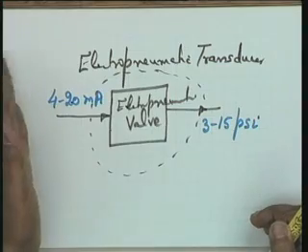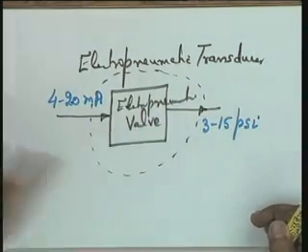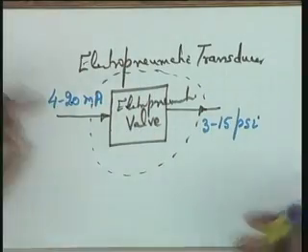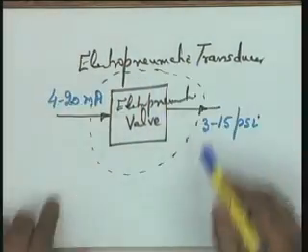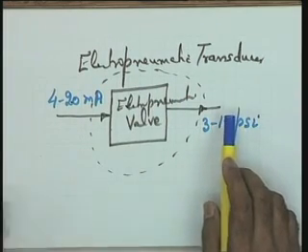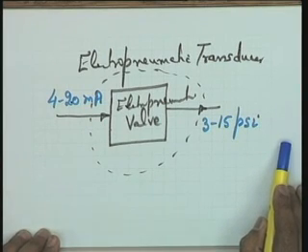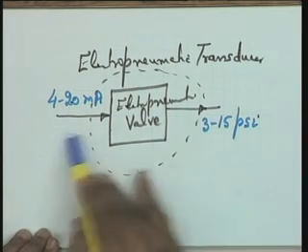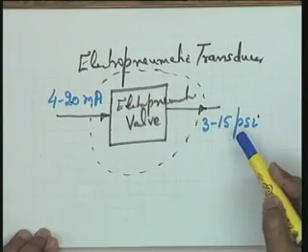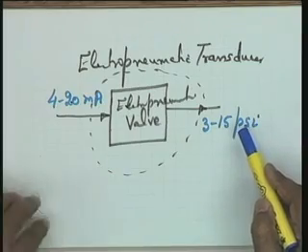If you have a voltage signal, convert it to a current signal and vice versa, so compatible voltage to current converters will be required. The industry provides a device which accepts 4 to 20 milliamperes as input and gives 3 to 15 psig as output, providing a suitable interface between the electronic controller and the pneumatic control valve to control the flow through a system.